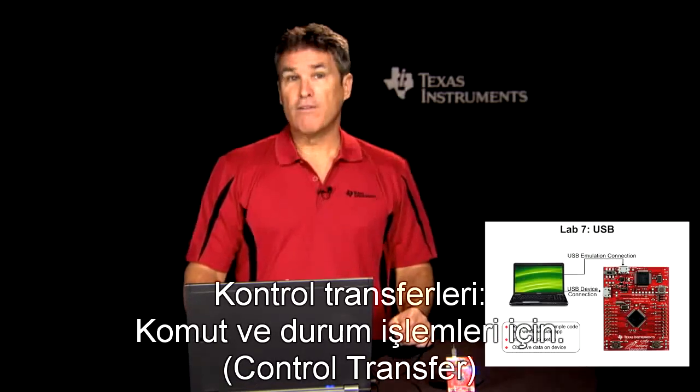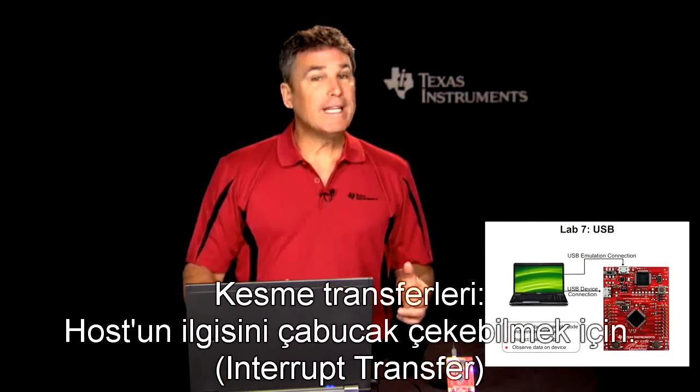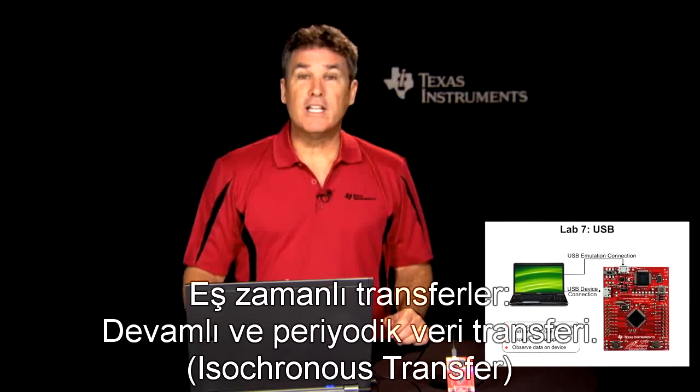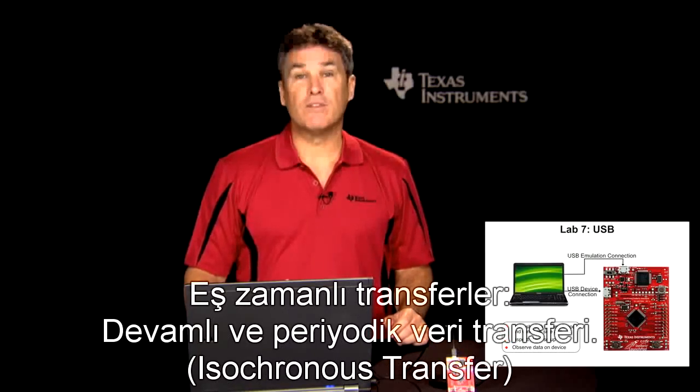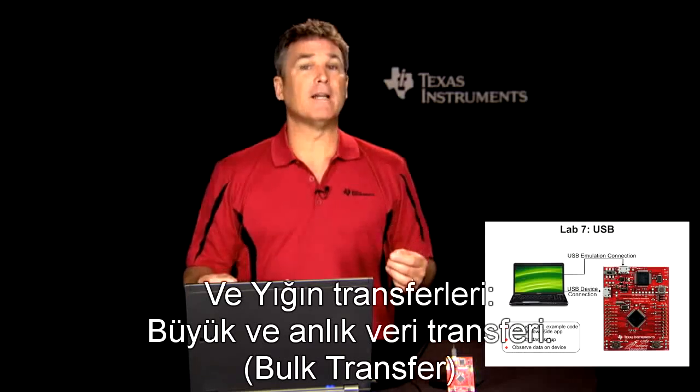Control transfers for command and status operations, interrupt transfers to quickly get the attention of the host, isochronous transfers, which are continuous and periodic transfers of data, and bulk transfers to transfer large, bursty data.